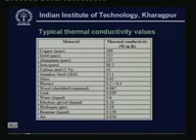And compared to metals, non-metals have still lower thermal conductivity. For example, glass has a thermal conductivity of 0.81 and plastics have 0.2 to 0.3, and cork has a thermal conductivity of 0.039. Typically cork is a bad conductor of heat, so we use it as an insulating medium, not as a conducting medium. And another observation is that compared to the solids, liquids have much lower thermal conductivity, and